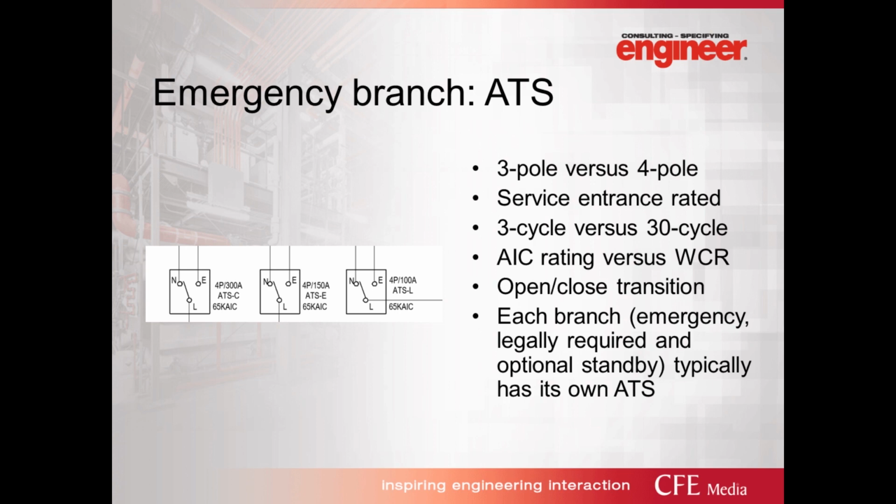3-cycle versus 30 cycles. Just like the switchboards and switchgears, ATS can be 3 or 30-cycle tested. Coordination study is a critical element that must go hand in hand with the design and specification of a safe and reliable emergency power system. The UL 1066 rated upstream breakers are required for 30-cycle ATS. Most branch breakers in low voltage systems are UL 489 listed. For these breakers, 3-cycle ATS is sufficient. Similarly to the switchgear, a 30-cycle ATS makes it easier to coordinate the system to assure power reliability.